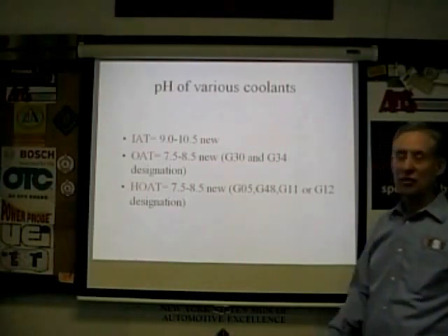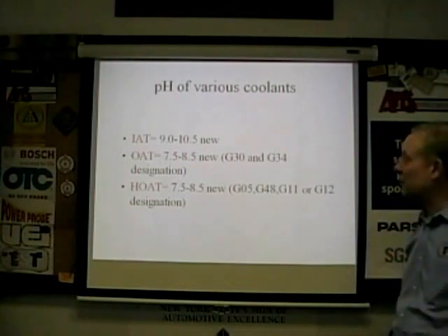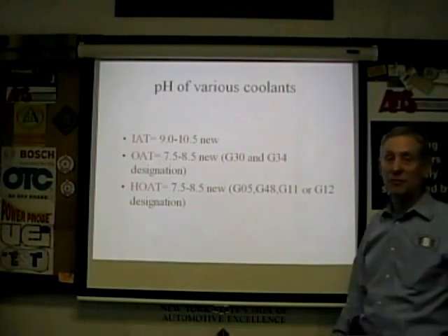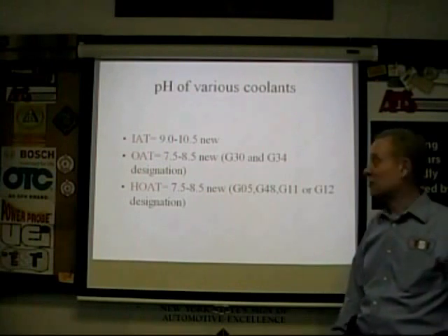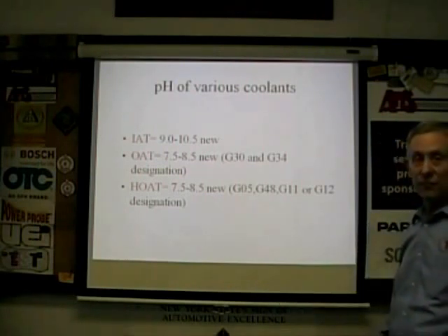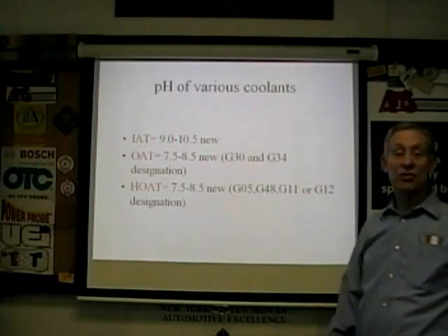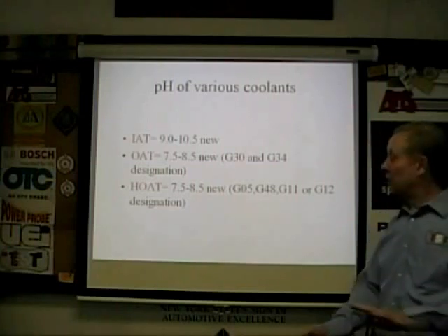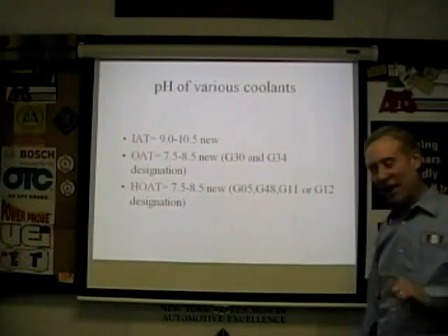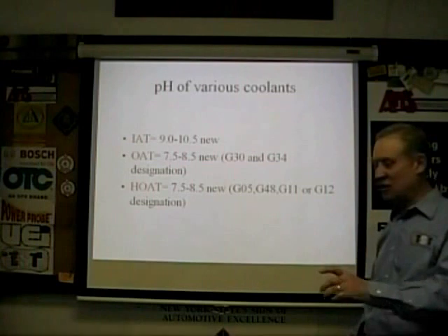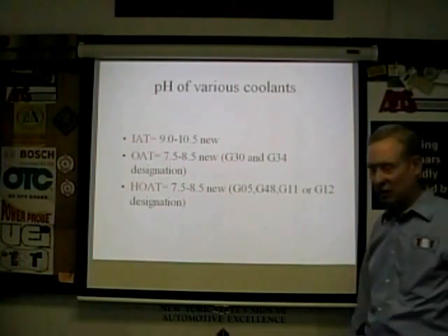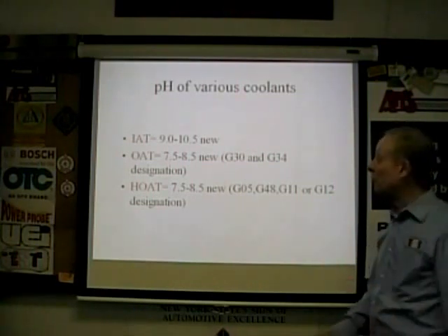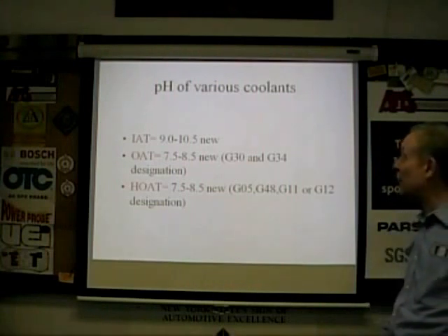Test it. There are also machines to test pH and so forth, not just strips for that, but the strips are there for the chemistry. And use those. Check your water, I guess. And check your water to make sure it's good water. And if in doubt, I'm saying it again, if you don't know what's in the system, flush it, make sure it's clear water all the way through, clean, clean, clean, and then fill it with the right stuff. Make sure it meets your manufacturer's spec.